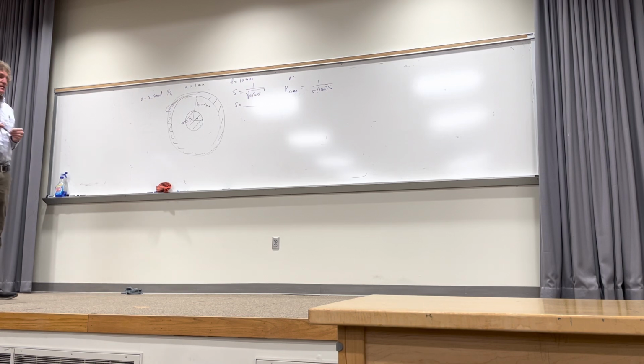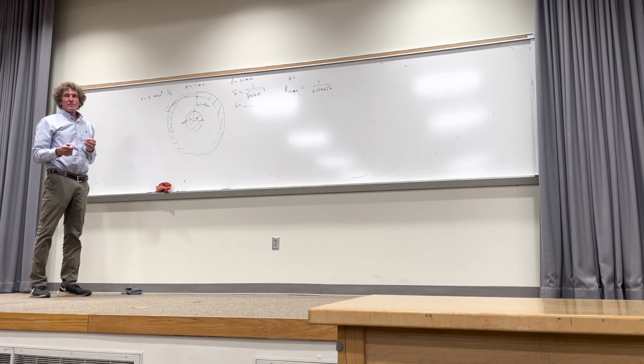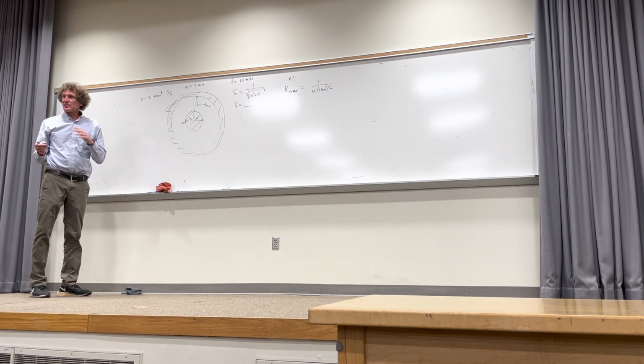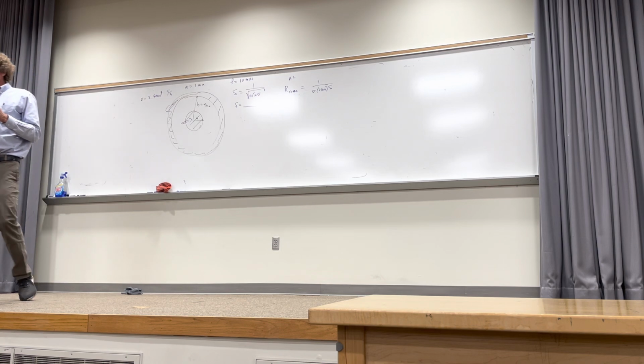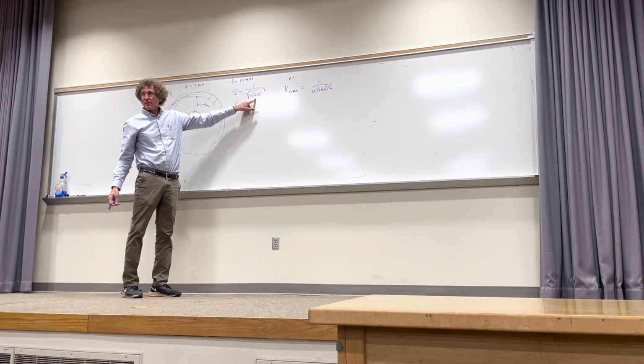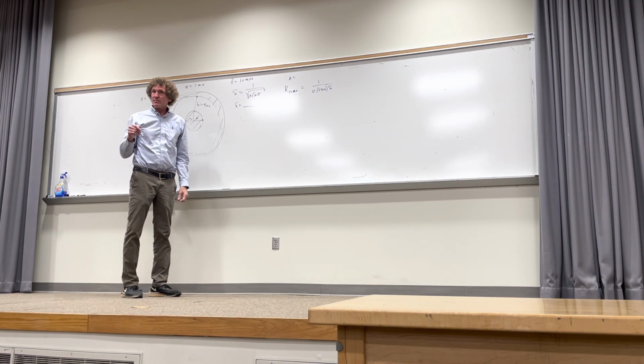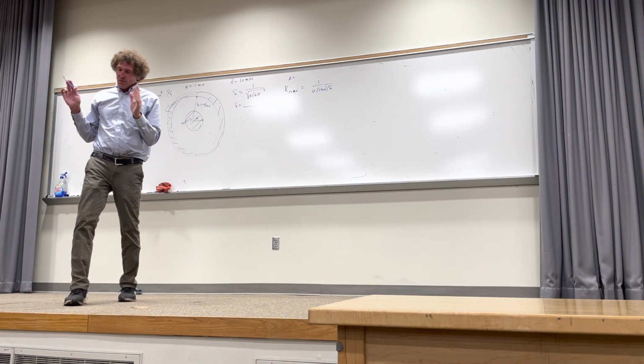Now, if it was steel, if it was 1045 steel, which is very common for a lot of things, the conductivity would be 5.8 times 10 to the 6th. It would be an order of magnitude less for 1045 steel. But also with steel, the relative permeability would be 1,000. So that would have a strong impact on this value right here. You all follow me? Order of magnitude less here, but 3 orders of magnitude greater here. So the overall effect would mean the skin depth would be even less in 1045 steel. Just keep that, or 1040 steel, pardon me.